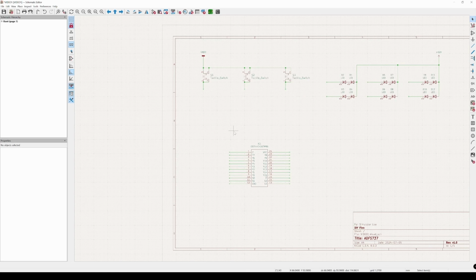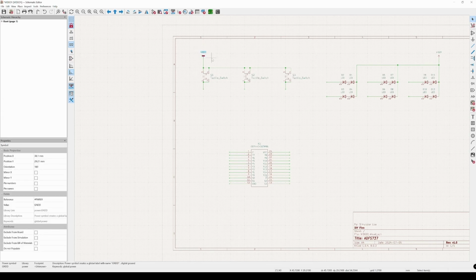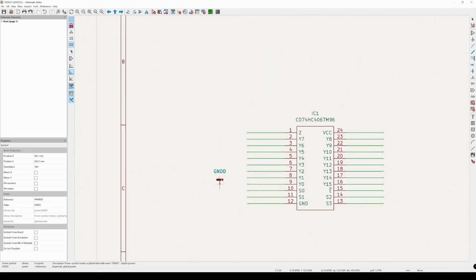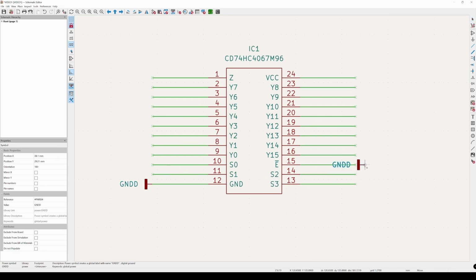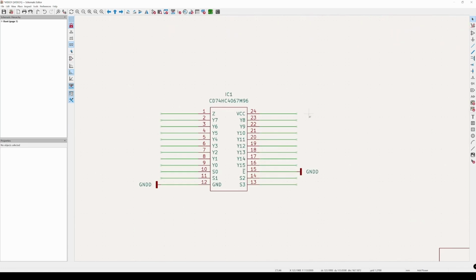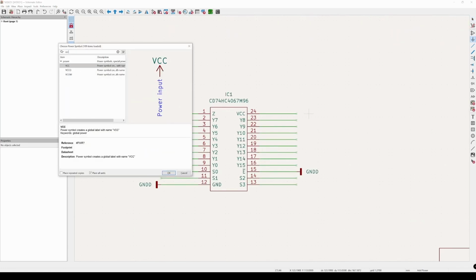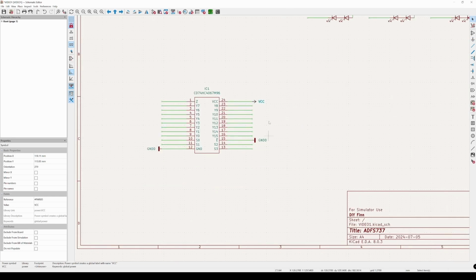So what I'm gonna do is to save some time. If you have already placed a component down or an indicator down, you don't need to add it again from the menu here, because you can just select it and Ctrl+C, Ctrl+V, copy it, and this will save you a lot of time. So we're gonna add the ground to here where we want them, and then what we'll do is add a VCC to the end here. So now we have the simple, clear ones here.